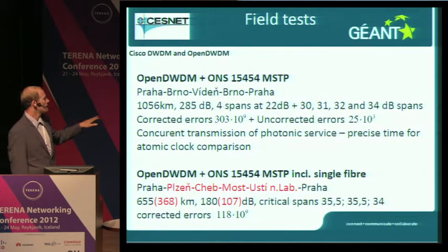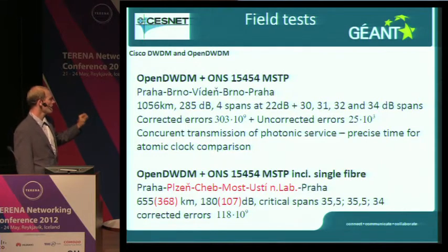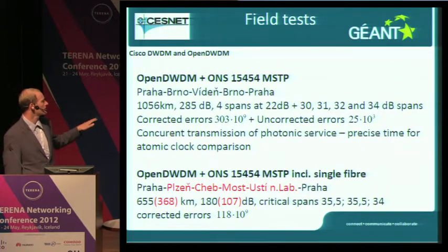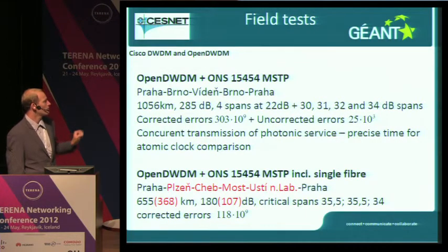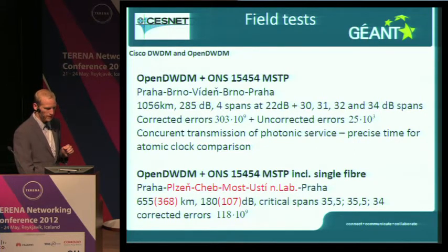There were also the photonic services running along. And the very last test was across the single fiber lines, and actually the loop was 655 kilometers long, and more than half of it was single fiber lines. There were 3 critical spans of 35 decibels, and the line was working with also some corrected errors, as always.